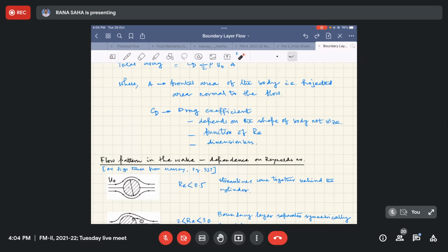Smoke is basically released from a nozzle, and you have a blower. Using the blower, you have an air jet coming out from a nozzle at a constant velocity. So that is your free stream velocity. Now you are injecting smoke in order to get it visualized, right? So that can be photographed. Flow visualization is a very widely applied technique for fluid mechanics experimentation.